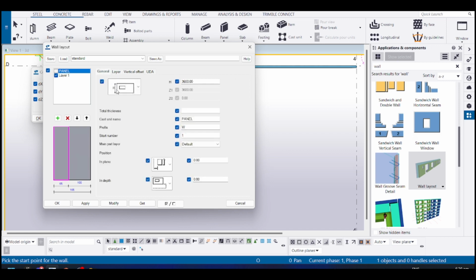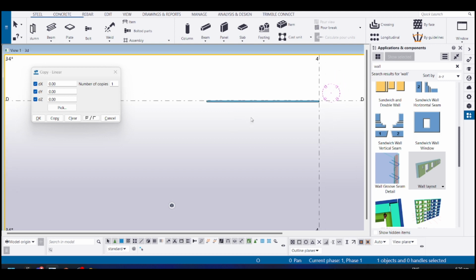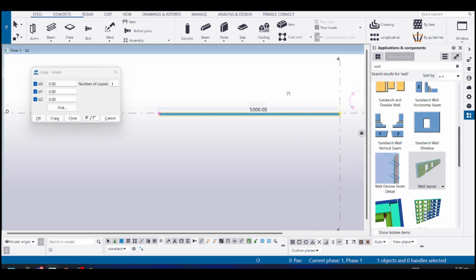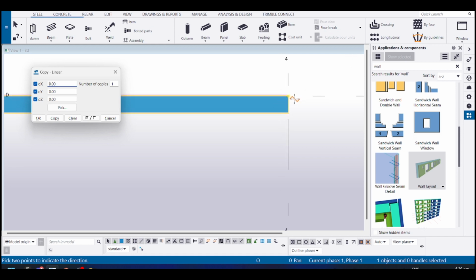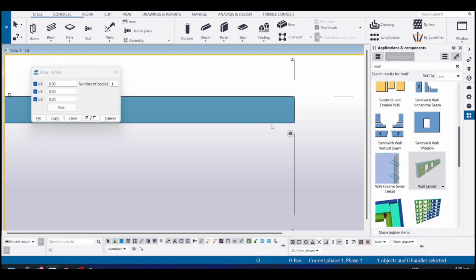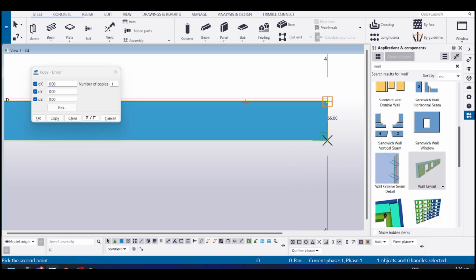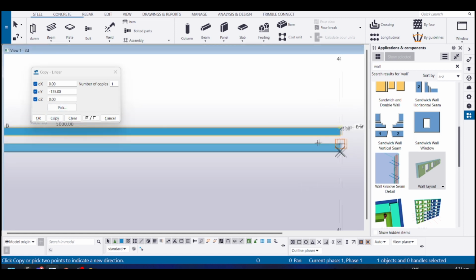There would be some videos that you could look at, but I'll basically show you how you can work your walls without a component. So I'll go here, and now the total wall thickness is 200. So I will select here, and I can click anywhere on this geometry, and if I hit control, that is a reference point now. When I give it directions and I hit 200, it'll take this 135 and I basically copy. So I have the two layers now.